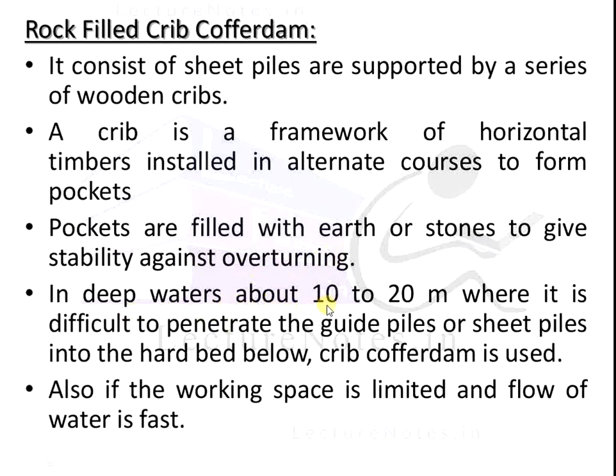In deep waters of about 10 to 20 meters, where it is difficult to penetrate the guide piles or sheet piles into the hard bed below, the crib cofferdam is used. Also, it is very useful where the working space is very limited and the velocity of the water flow is fast or more.